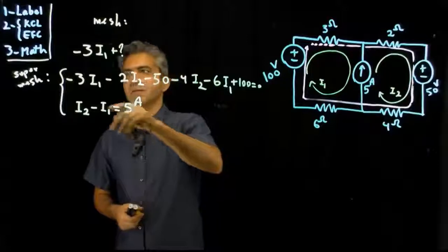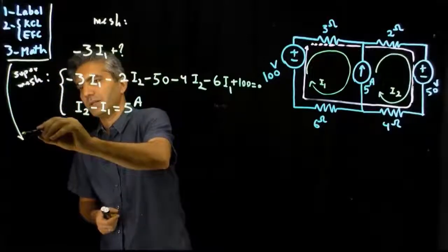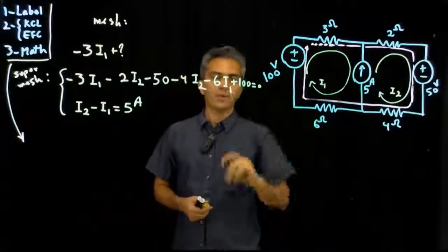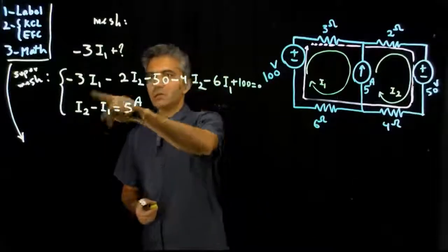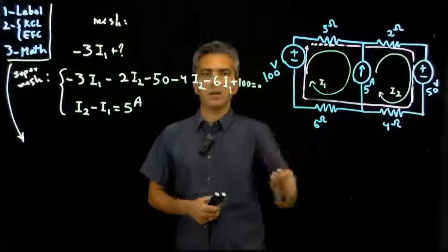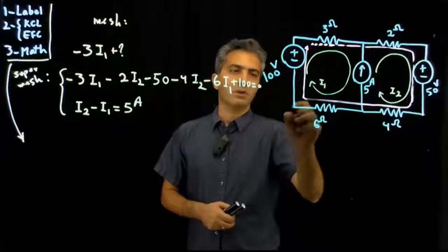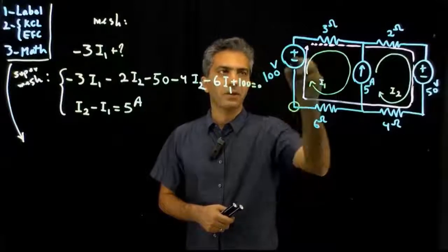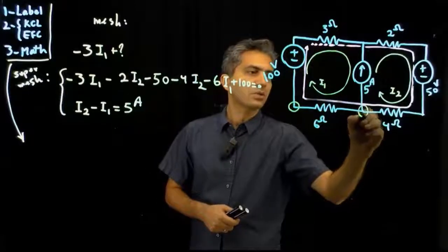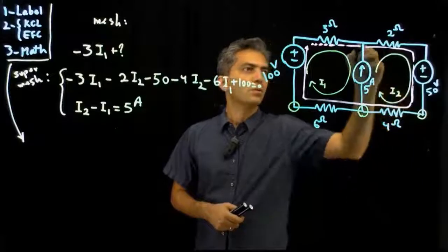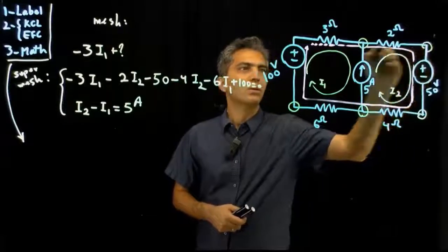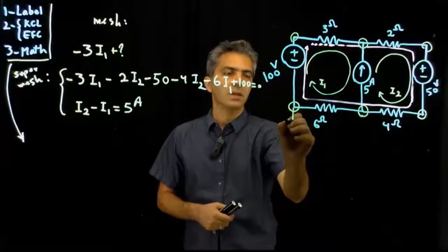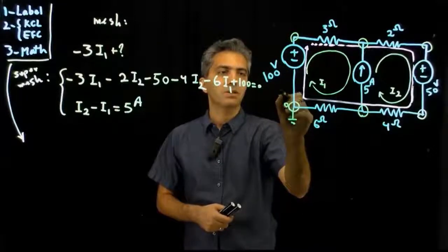Now, let's resort back to the basic universal approach and see how we could have done that without resorting to defining any new concept. With our method, we have to actually define nodes. That's a node, this is a node, that's a node. Then I'm going to take one of these as my reference. This would be my 0 volts.